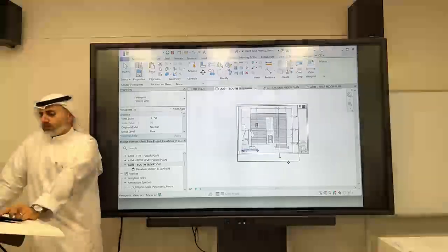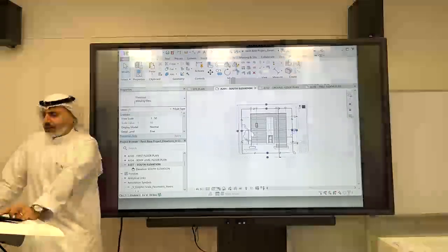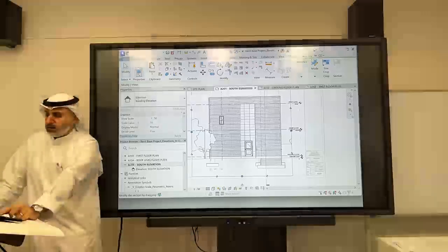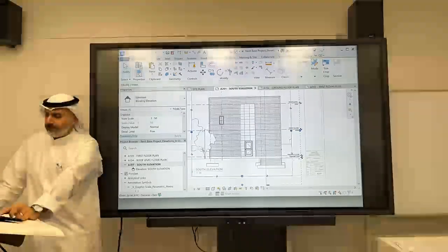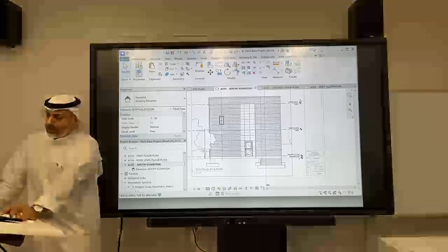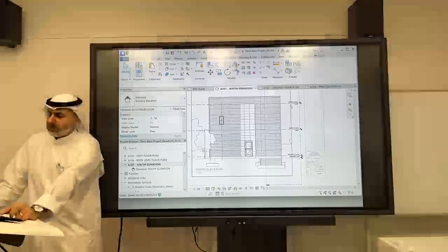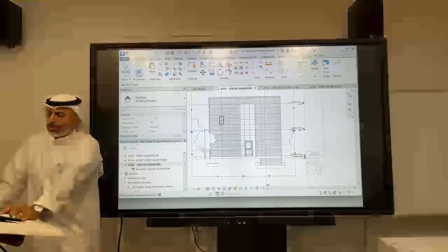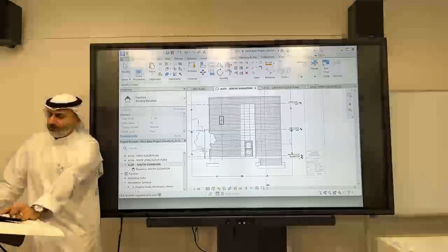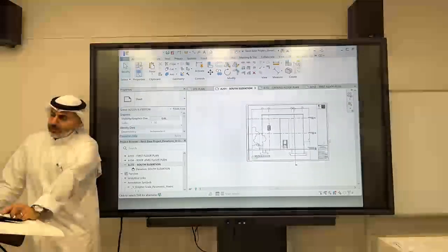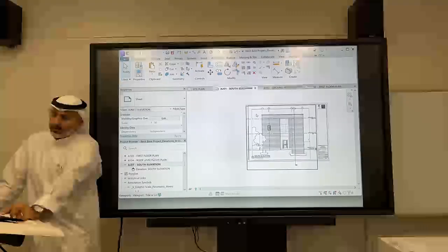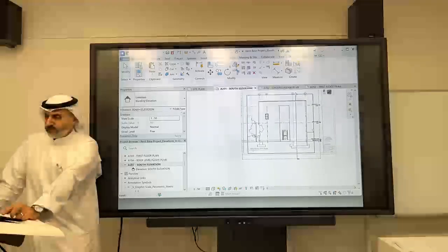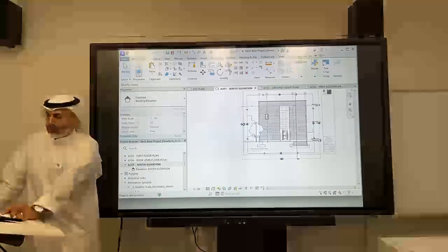So when you bring in the edge of your crop view, you will notice that these levels are moving as well. Take it to somewhere where you have a decent margin on the sides, but it's not stuck. Don't let it be this close to the edge. Give it some buffer. But then let's go back to the view and also do it on the other side so that nothing is popping out of your view.